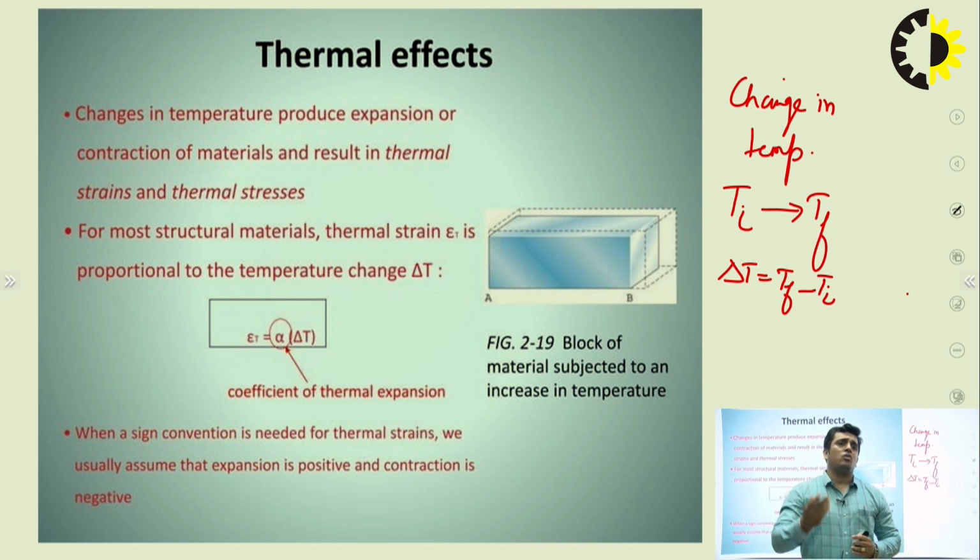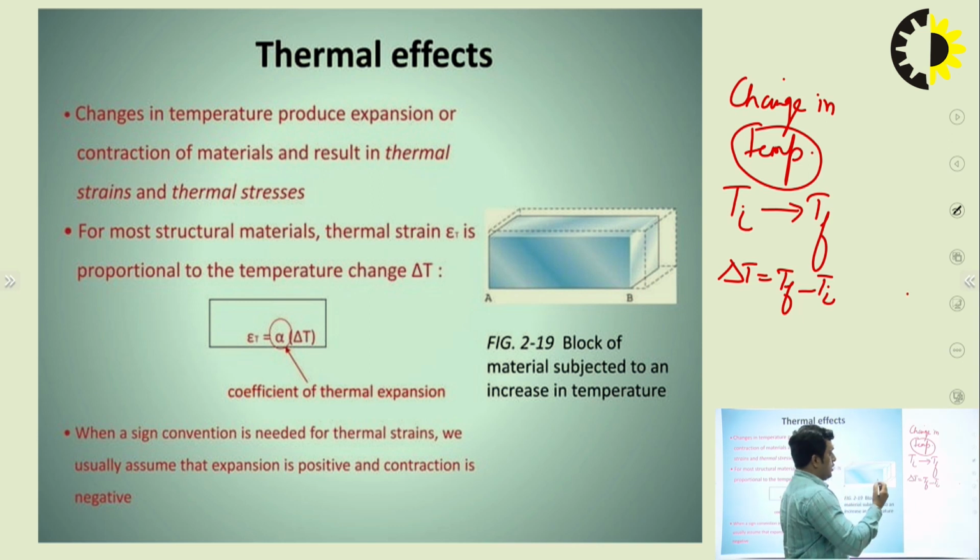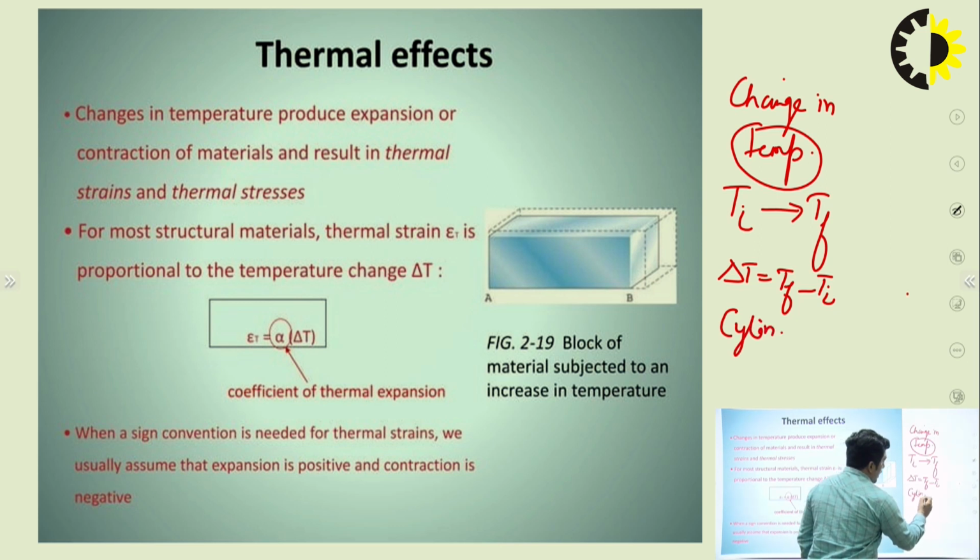So that's why I have said that whenever a component is heated or cooled, its expansion or contraction starts. Either it is going to expand or it is going to contract. If it is expanding, then it is thermal expansion. If it is contracting, that is thermal contraction. Means when we hear the word thermal, we must focus on the term temperature. So thermal stress is totally dependent on the change in temperature whenever a component is heated or cooled.